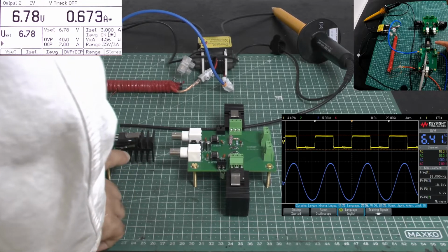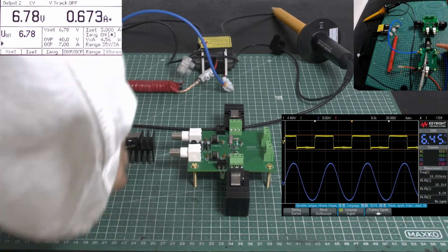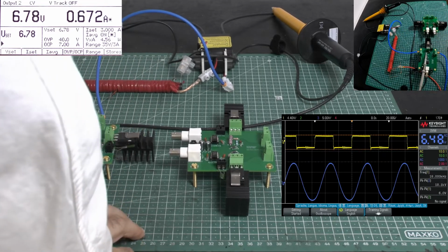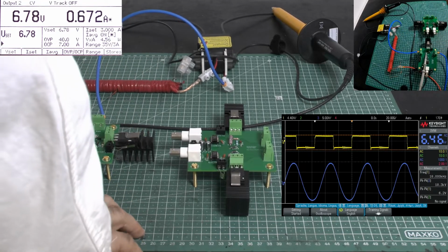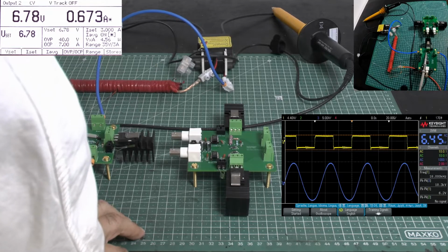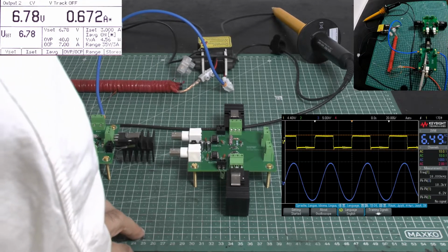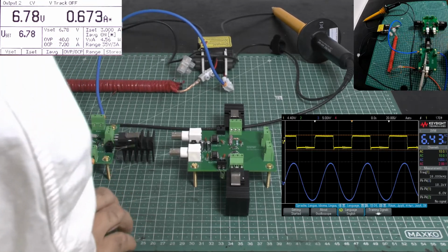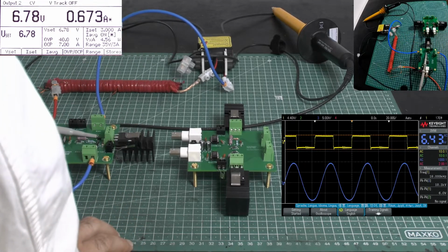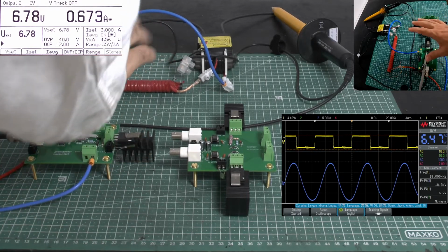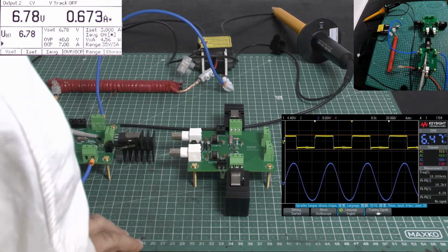But it is not only the gate capacitor which does that, it is also the inductor which reduces the ringing coming back as a back EMF from the high voltage transformer via the primary. So the inductor is important and we should use it to reduce all kinds of disturbances and back EMF issues, specifically here with a flyback transformer.